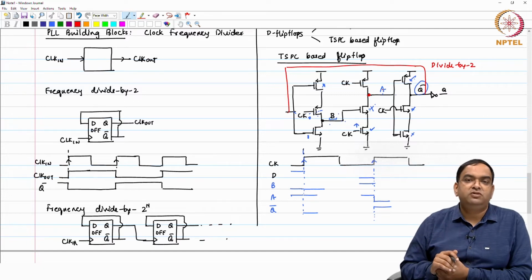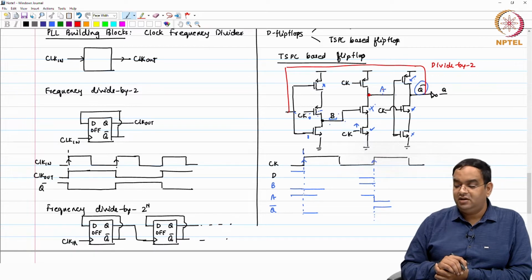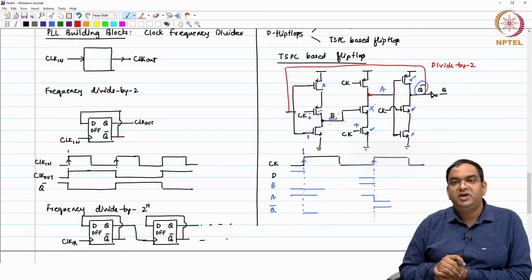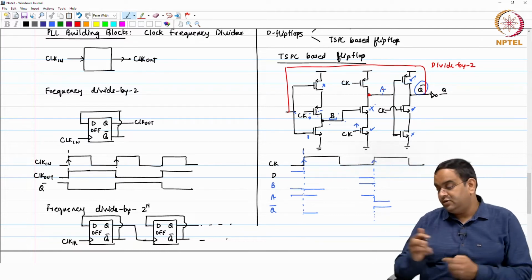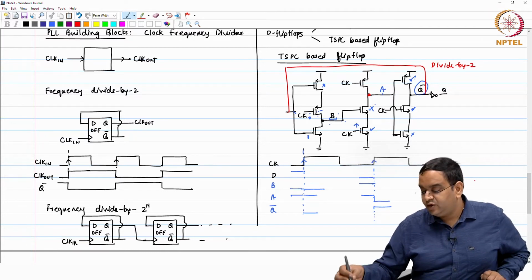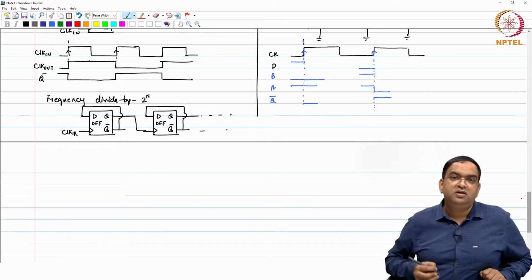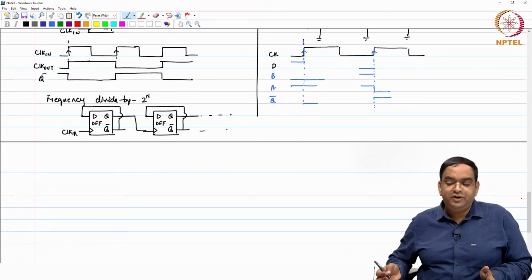Due to the subthreshold current, the leakage will be there, and then you will have a different value at these internal nodes. So, normally we do not use these TSPC based flip flops for frequencies lesser than 100 megahertz, but this is very much technology dependent. Okay. For lower frequencies, it is not advisable. And the reason is because the nodes discharge over a long on or off duration.